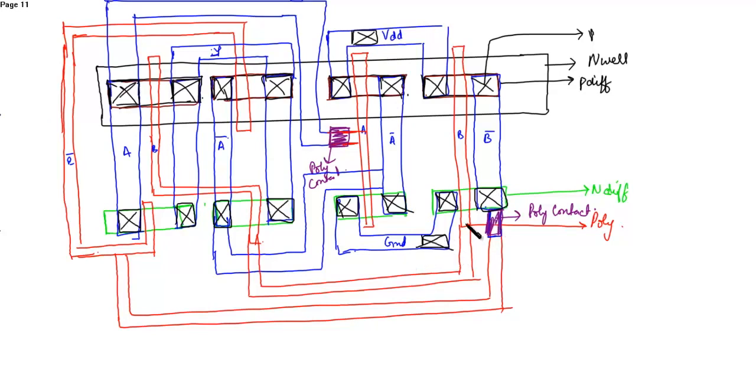Okay. Now after placing the contacts, you can just verify once more whether all the connections are done. Inputs given, output is labeled, VDD, ground. Okay, so these are the two inverters. These two are inverter 1, inverter 2, transmission gate 1, transmission gate 2.